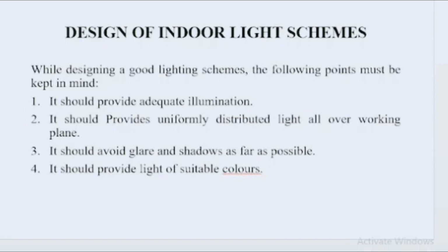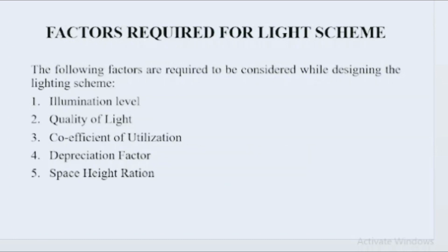Next, factors required for light schemes. What are the factors mainly required to design the lighting schemes? You have to keep them in mind before designing. So first one is illumination level. Next one, quality of light. Next one, coefficient of utilization, depreciation factor, space height ratio.